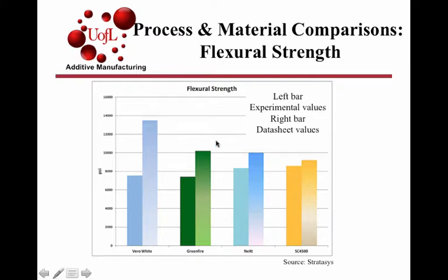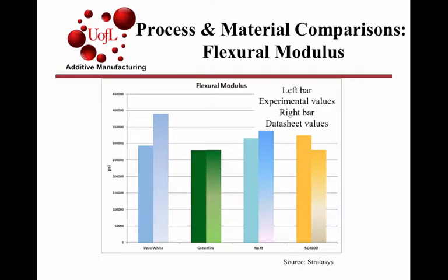You also end up having flexural strength comparisons between the parts that are printed by the two different processes as a type of example. And in addition, there's a strength in the flexural modulus. Okay, so comparable material properties can be obtained. You can tend to get more of the elastomeric contributions and elastomeric formulations printed through the material jetting method.